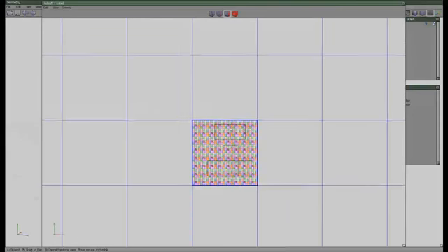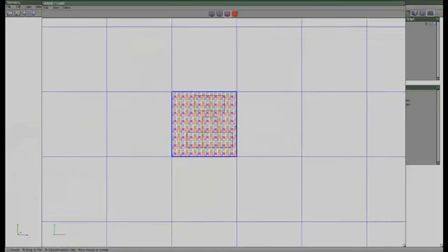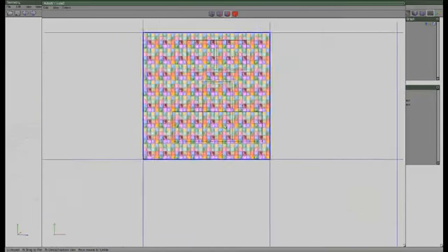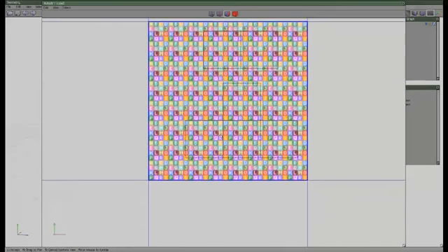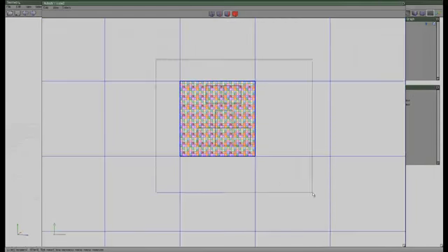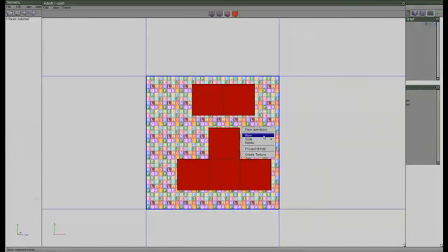You can change the position by clicking the middle mouse button so that your pointer disappears, and then when you click again, hold your middle mouse button, you can actually pan the view. So again, click the middle mouse button, click it again, hold it, and then we can pan the view. So that's really it as far as navigation goes. Just scrolling, panning, that's really all you need.